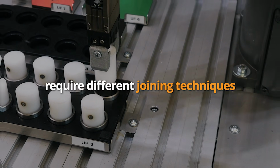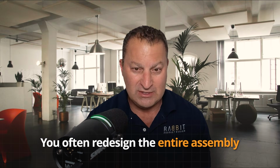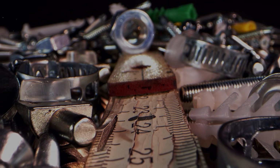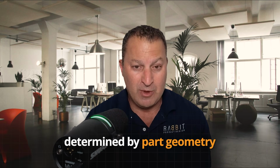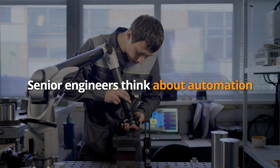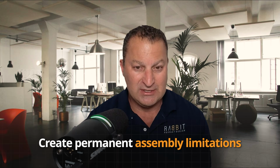Both slow production. Material choices influence assembly methods as well. Different materials require different joining techniques. Change the material later, you often redesign the entire assembly. Fasteners are another hidden factor. Each unique fastener adds time. It also adds inventory complexity. And tool changes during assembly slow down production lines. Assembly fixtures are determined by part geometry. Complicated geometry requires custom fixtures, which adds setup time to every production run. Senior engineers think about automation potential immediately. Junior engineers focus only on making a prototype work. And those early decisions create permanent assembly limitations.